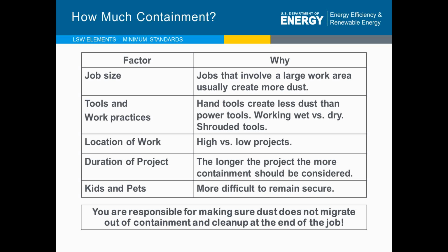The duration of the project. If your weatherization project goes on for multiple days, you better do a better job with containment because you're probably going to be leaving that containment up, and you certainly do not want occupants to get access to it. You certainly don't want dust and debris at the end of that day drifting to areas that are clean. Matter of fact, you would clean that area before you left it for the day.